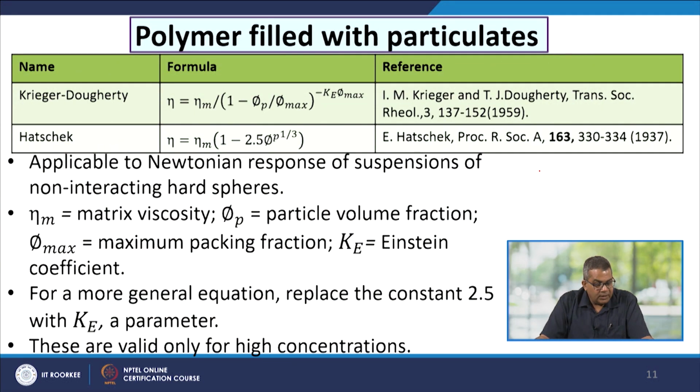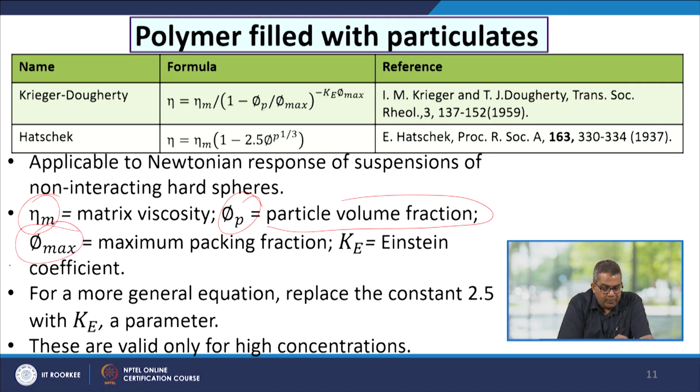or references. Similarly, the Krieger-Dougherty equation and the Hartwig equation. So, all these equations we have enlisted as a reference, and as per the case they can be utilized. Now, these are applicable to the Newtonian response of a suspension of non-interacting hard spheres. Here eta_m is the matrix viscosity, whereas phi_p is the particle volume fraction in every equation, phi_max is the maximum packing fraction, and k_e is the Einstein coefficient.